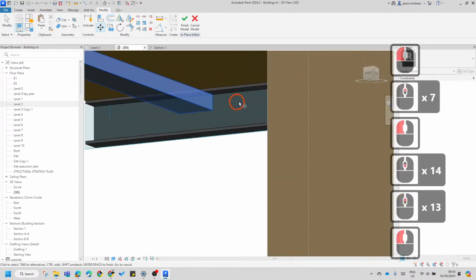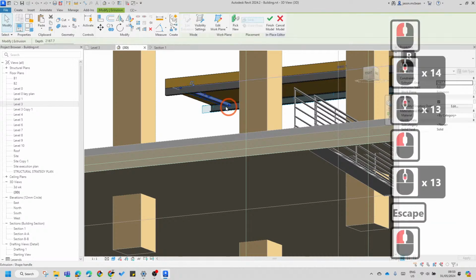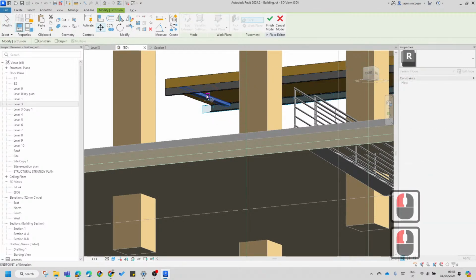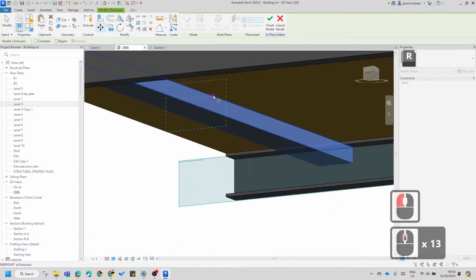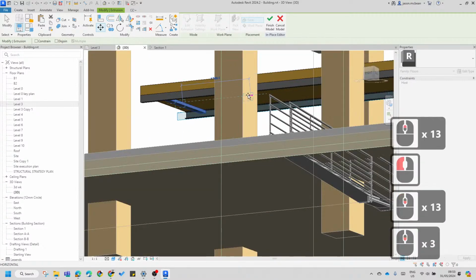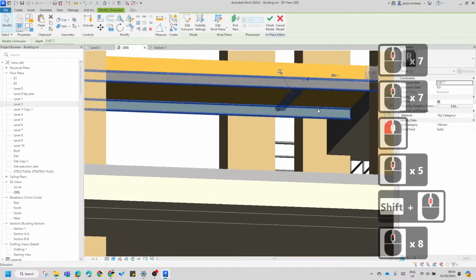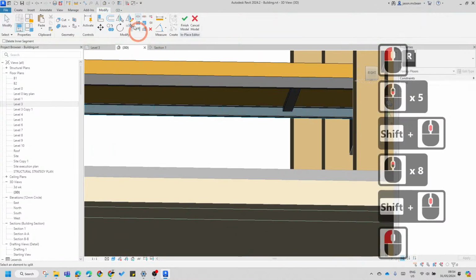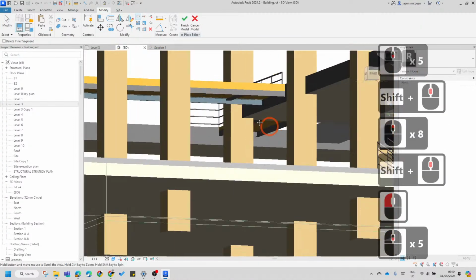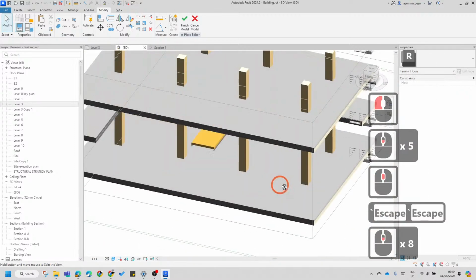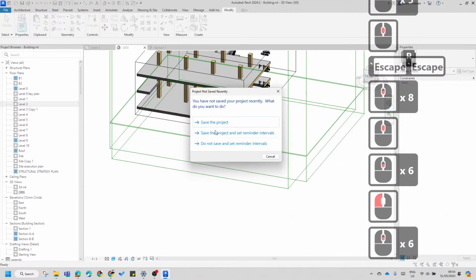Sometimes it doesn't like to snap, so just be careful, okay? You might have to go to a section view. That would be easier for now. See, now it's wanting to use this middle point here. So there. It'll snap. Put it back to here somewhere. I'm just showing you this quickly. Now you can use the array command. So you're going to say array, but now this is where the section tool might come in handy. So finish this.